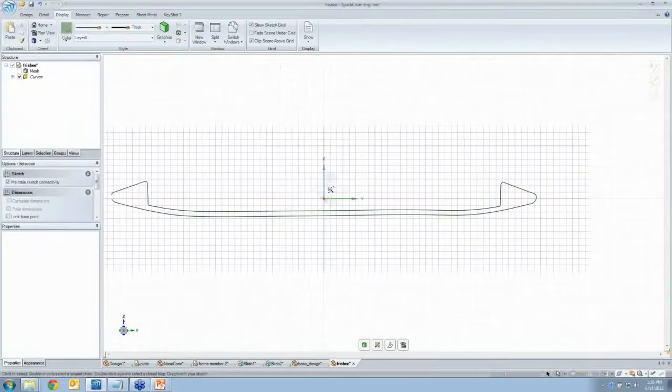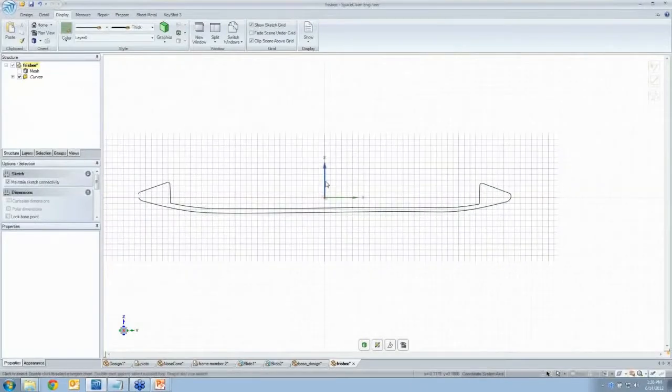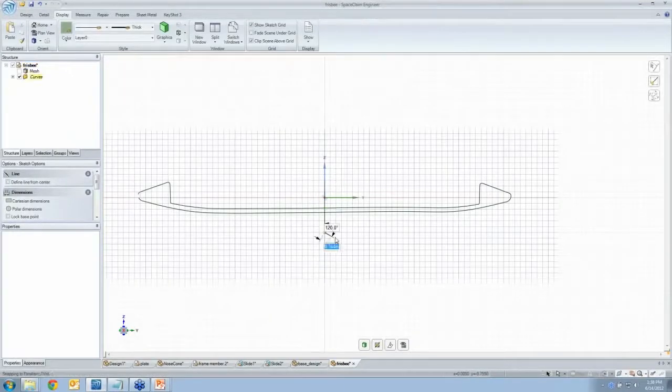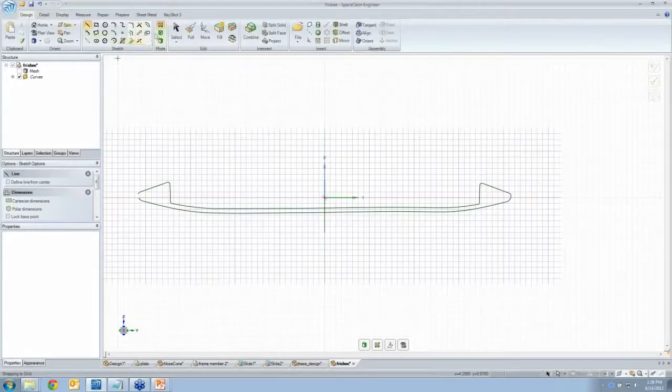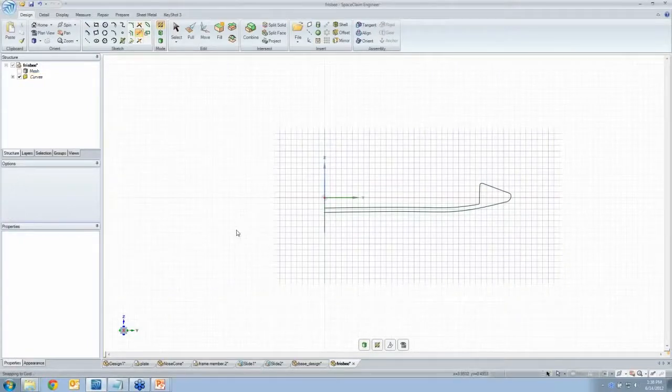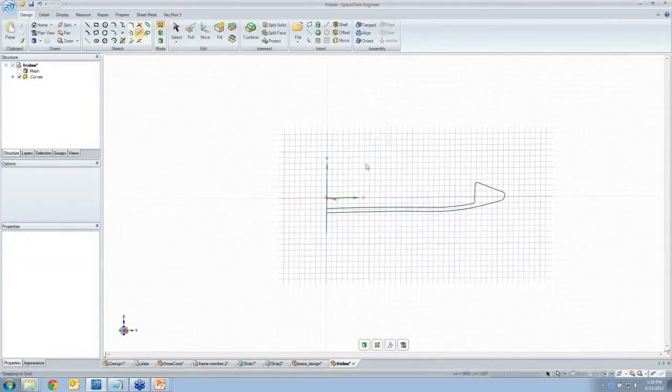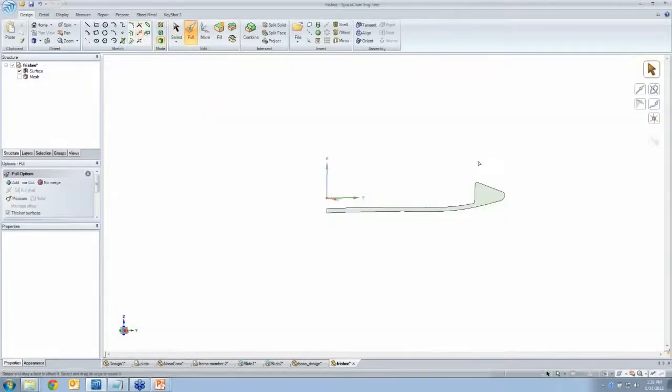Now, for me to recreate this, I really only need one half of it. I'm going to skip the left-hand side, right? That's not relevant for me because it's not complete, so I'll use just the right-hand side instead. So I just use a couple simple sketch tools to get this in a useful state and get rid of everything on that one half. Now I have a closed loop set of sketches, or sketch entities, vectors, that turns into a surface.